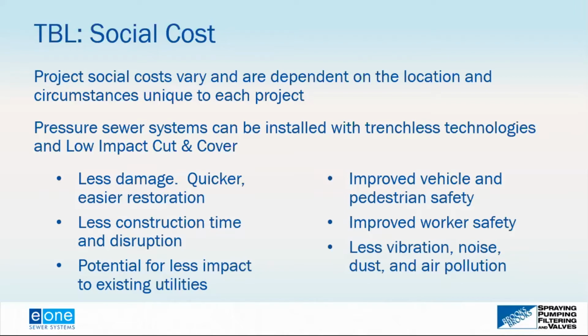Another thing I learned in my early days doing construction inspection is after you went through with the gravity sewer system, there seemed to be a lot of homeowners that had cracks in their foundations, and it was caused by the project. Now, those cracks look pretty old to me, but I'm not the one who makes that determination. But it's not uncommon, and we had to do some rock blasting in eastern Massachusetts, a lot of granite, and you're blasting all day. So you're going to have broken windows, broken or cracked foundations. With the pressure sewer systems, you're able to do that horizontal directional drilling.